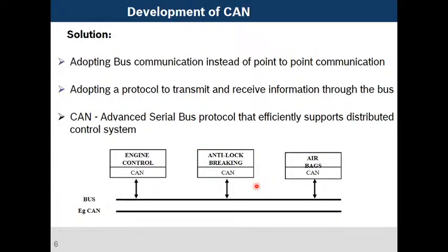As I have already mentioned, we adopt bus communication instead of point-to-point communication. Information is transmitted and received through the bus, not for individual ECUs. Throughout the bus, the information will be available. Whichever ECU requires that information will take the data from the bus.